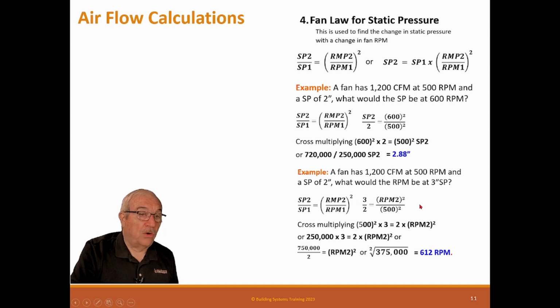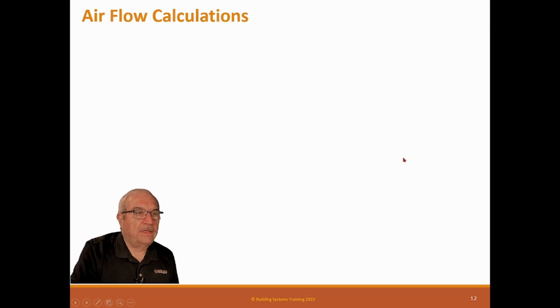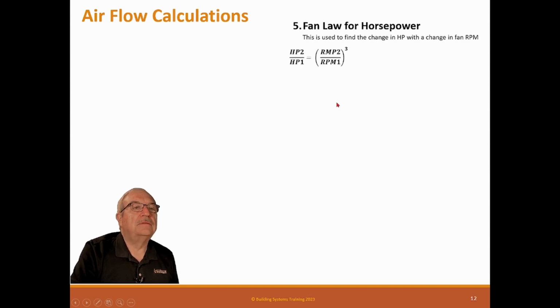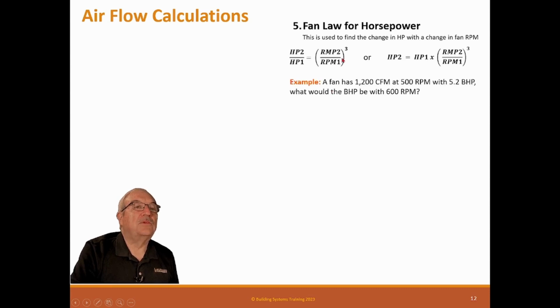We use these all the time. You need to become really familiar with these. The next fan law is the fan law for horsepower. Horsepower 2 over horsepower 1, same thing we've done before, except you do notice this is a cube in there now and not just a square.